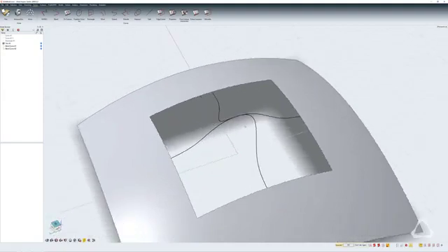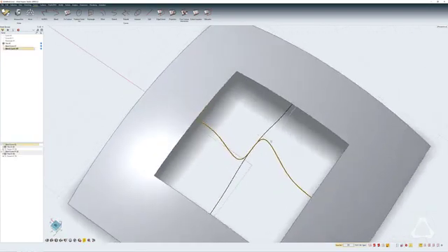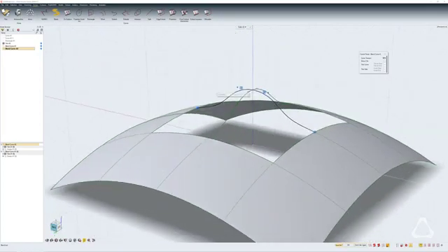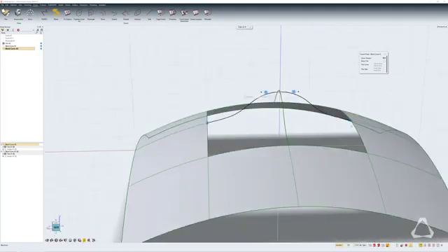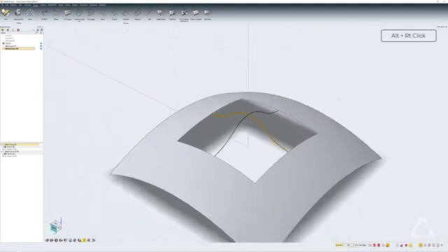In order to edit the shape of the curve and also the property of the middle point, go into edit mode, select the point and change it from curvature to just a positional point. So this means it's driven by the other two endpoints. Right click, swipe. Now go to the loft.